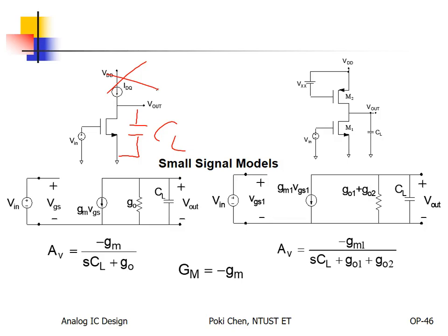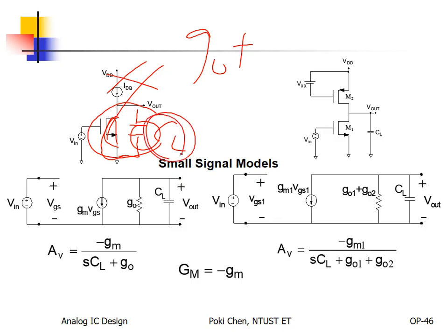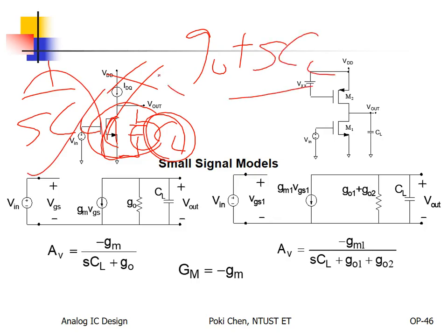Then your output conductance, because they are connected in parallel, right? So the overall output conductance is your conductance plus his conductance. For impedance, we have, right? And for conductance, congratulations. That's it. And what is output resistance? 1 over this. Okay? And that is output conductance, output resistance.